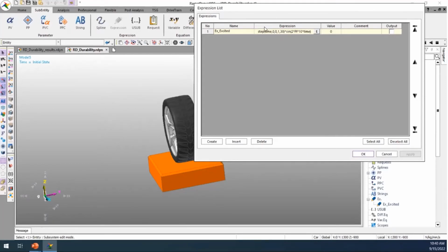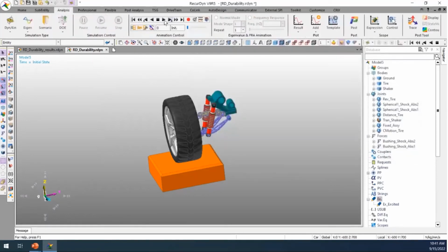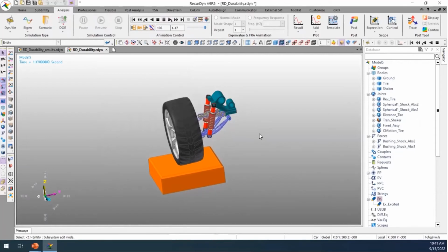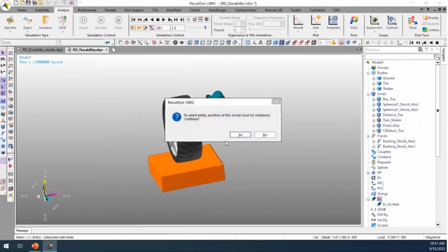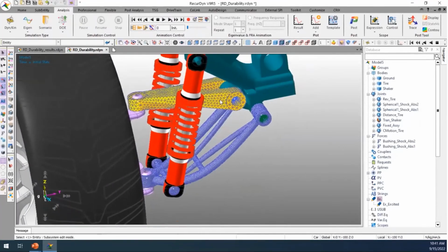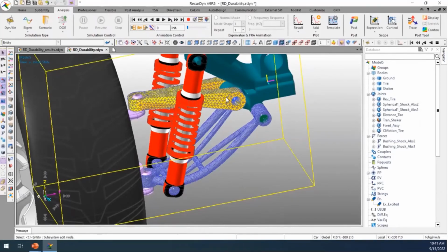I don't have to know how this is all organized, but I just wanted to give some background on what's happening. We can play it back. It starts off with a super low amplitude, and then it's ramping up over time. We've got 1.2 seconds of simulated time, including these 2 meshed bodies. You can basically think of them as FE bodies that are being solved in a transient simulation, and they're connected to rigid bodies where the deformation doesn't matter.